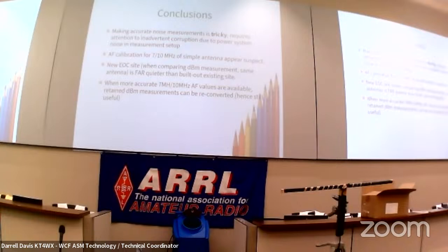I've got solar panels. And they go into a charge controller. And the charge controller is a switcher. I mean, all charge controllers are switching power supplies. So they're just RF generators. And their antenna is the wiring to the panels. So that's the first noise generator.